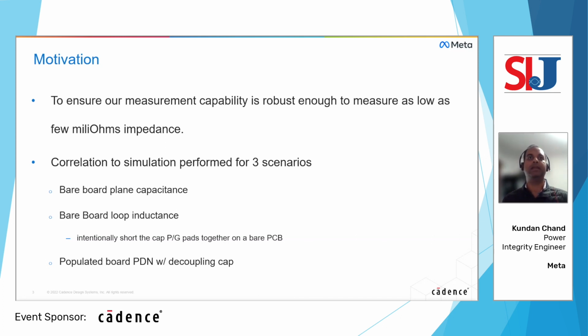Next step, we went ahead and intentionally created a short on one of the capacitor pads so that we could measure the bare board inductance in the tens of megahertz or hundreds of megahertz range. And the reason we did that is because we wanted to assess our measurement capability to be able to measure those few picohenries or few tenths of picohenries accurately. So that was the second step.